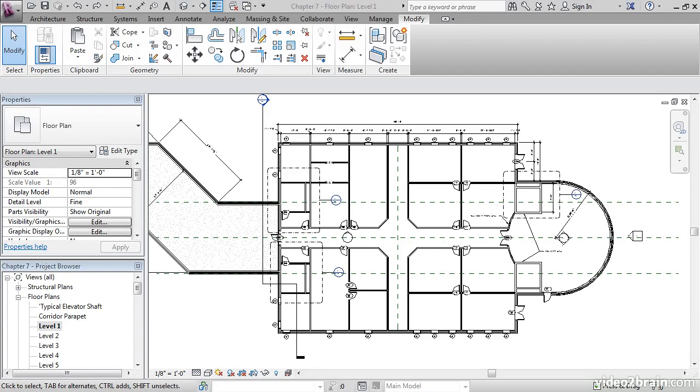In this lesson, we're going to physically split the floor's top layer, add an alternate material, and pitch the floor to a floor drain. The problem with assigning one material to an entire floor of a building is the fact that not every room is going to have the same material. I've seen people actually put a different floor in each room. Please don't do that until you see how Revit wants you to do that.